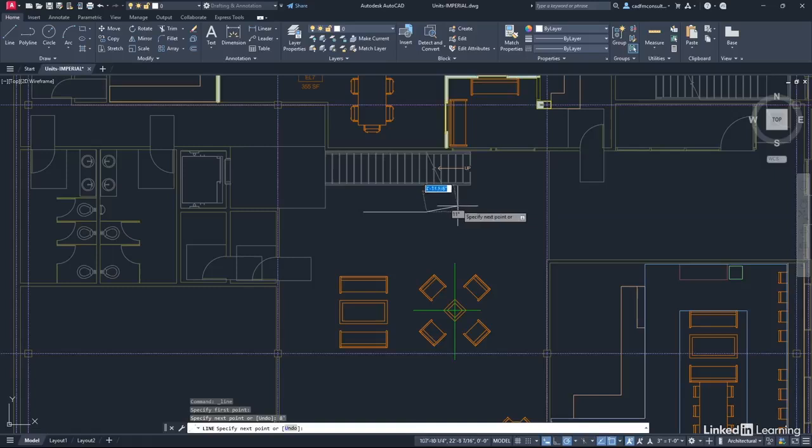Well, first thing we'll do, we'll just right click once and select undo on the shortcut menu. That will take us back to the start point again. Can you see? So we've lost that line segment, that 8 foot long line segment. So I'll drag horizontally to the right. And what I have to do is I have to type 8 feet dash. AutoCAD now thinks, oh, you're going to put some inches in there. And I'll put 6. And then it's like the speech quotations. Exactly the notation as if you were writing feet and inches with a pen and paper. So that is now 8 foot 6 inches. Press enter. That is now 8 foot 6 inches long, that line.